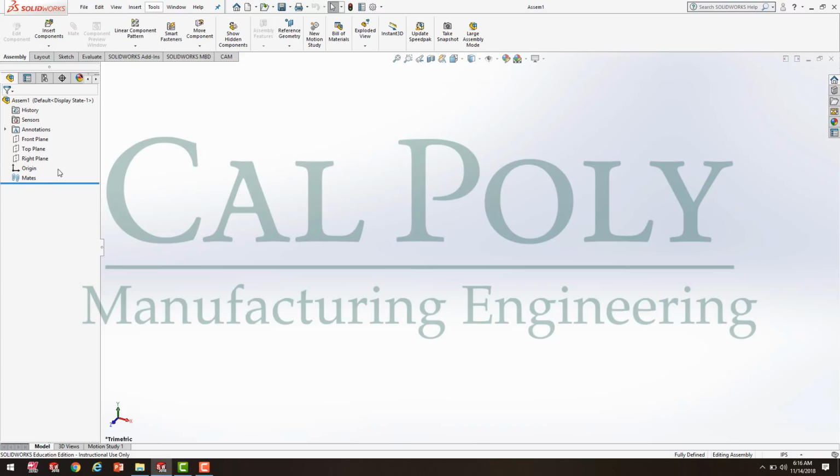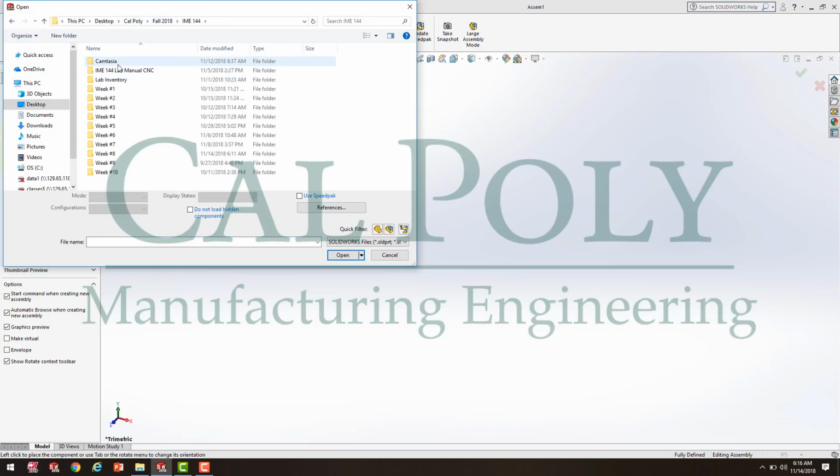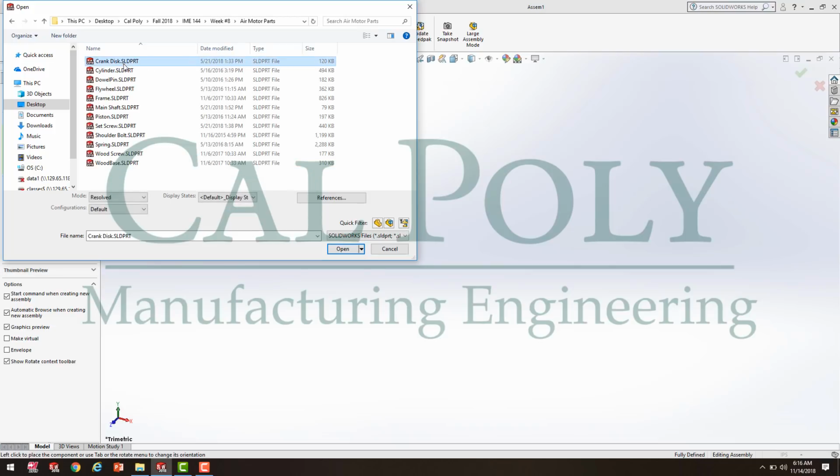Now, looking over here on the file tree, you're going to see we've got our mates, our origin, and our planes right now. So the first part we bring into the assembly is our base component. In order to bring that base component in, we have to hit the Insert Components button and go select our files. So we go find where we've saved everything. And for the air motor, the base component is the wood base. So what we're going to do is insert the wood base by pressing Open.